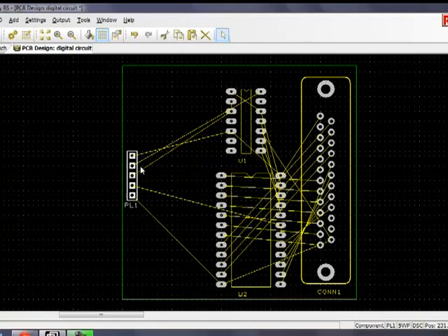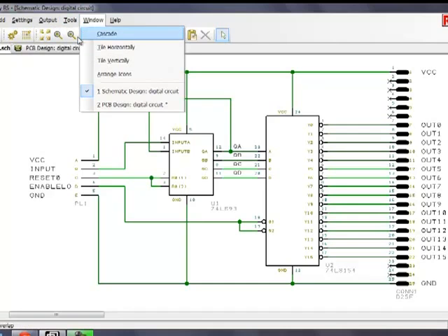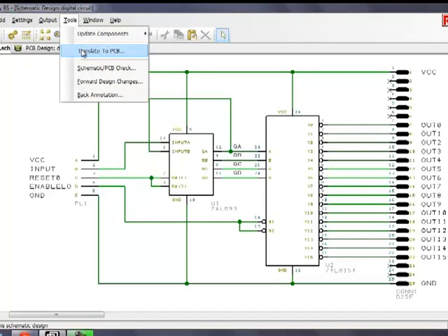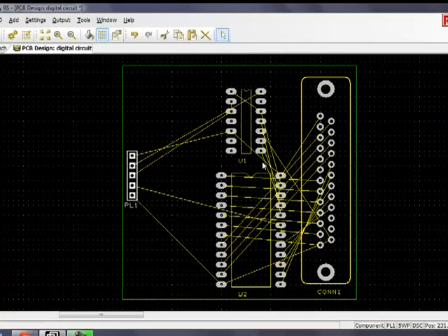So just to summarise, what we've done this week is look at the schematic circuit here with the two digital devices and the plugs. We've used the Translate to PCB command. It took us through the wizard to set up the number of layers on the board, the size of the board, and how we wanted to deal with the components, and we ended up with this file.